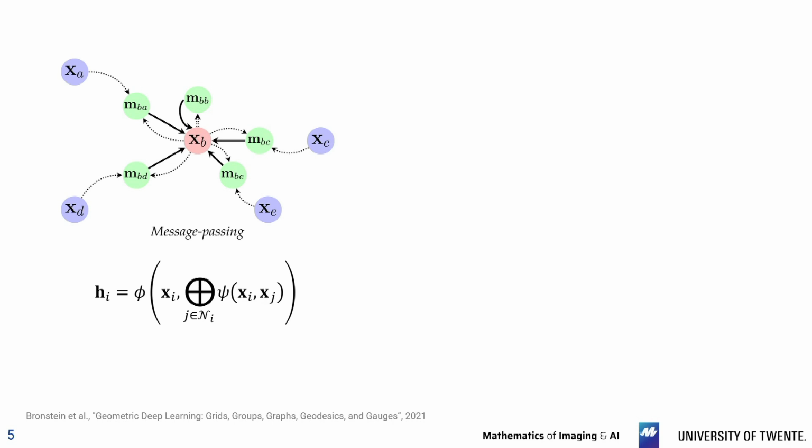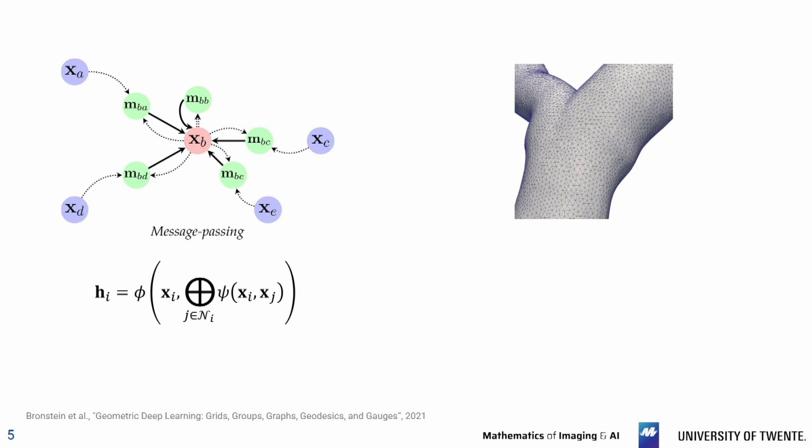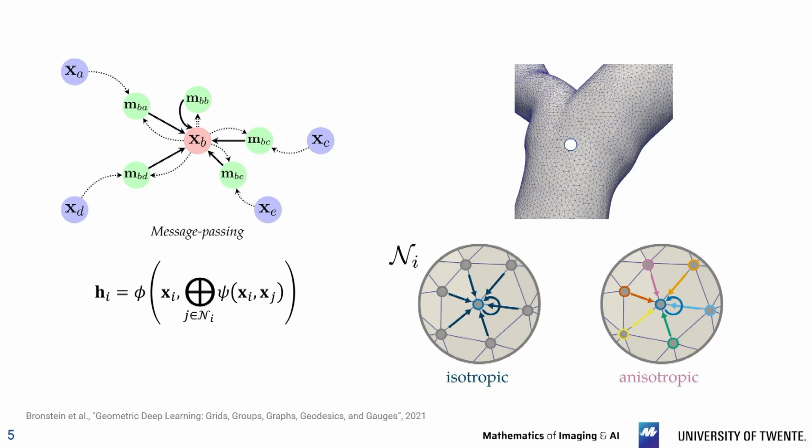And the interactions are modeled using, for example, a neural network, psi. And then to update the signal in the graph H, we just have to aggregate all the neighboring nodes and we get our update in each step. The message passing algorithm and graph neural networks in general are easily applied to meshes, because meshes can be seen as graphs by just dropping the information about which nodes belong to which volume element, leaving just the nodes and the edges in a mesh.